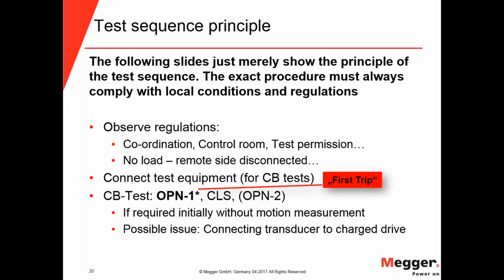So this gives you important information of the long time condition of the circuit breaker. You know, from previous webinars also, that the coil can get stuck due to dried grease or corrosion or something like that.